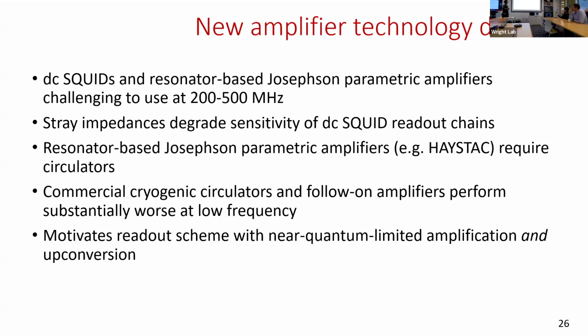Below 200 megahertz, DC SQUIDs have been a workhorse for about the last 60 years. However, when you go above 200 megahertz, for reasons of stray impedance, so intercoil capacitance on the input coils of the SQUIDs, for example, you get degradation of the sensitivity.